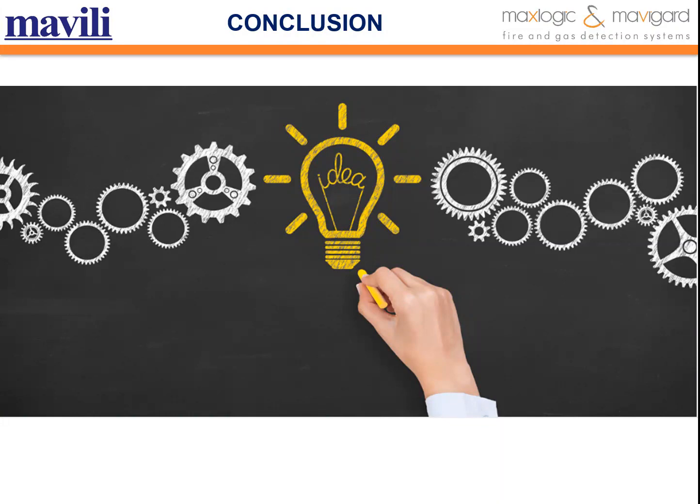As a conclusion, fire alarm buttons are one of the important devices of a fire detection system. When a person in the area notices the occurrence of a fire, he can inform the fire alarm system through the call points. For this reason, the placement of the manual call points and the mounting height are very important. When designing, the items in the EN 54-11 standard should be taken into consideration.